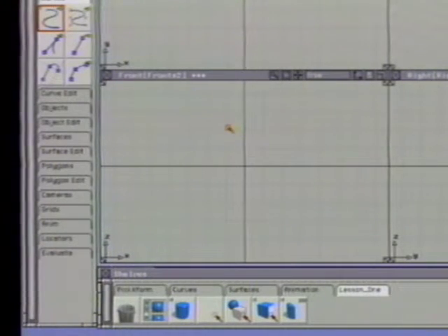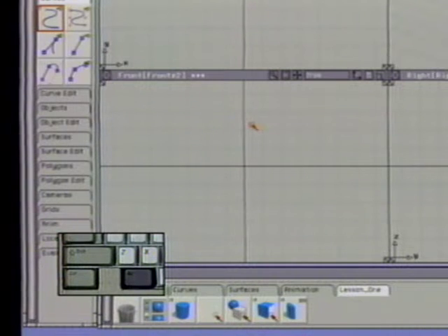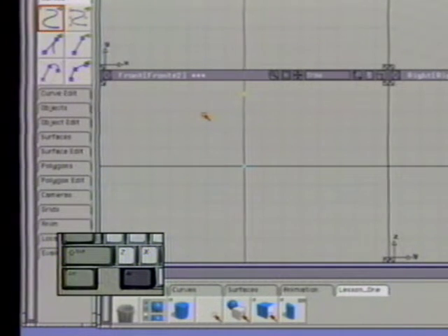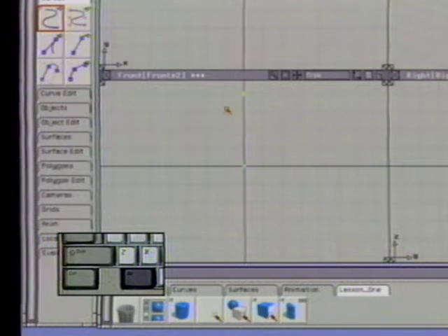Go to the Curve section of the tool palette and choose New Curve. Click in the title bar of the front window to make it active. Press the Alt key to temporarily turn on grid snapping and place the first CV at the Z-axis, 4 grid squares above the X-axis at point 0, 0, and 4. Because you'll revolve this curve around the Z-axis, either the first or the last point of the curve must lie directly on this axis line.